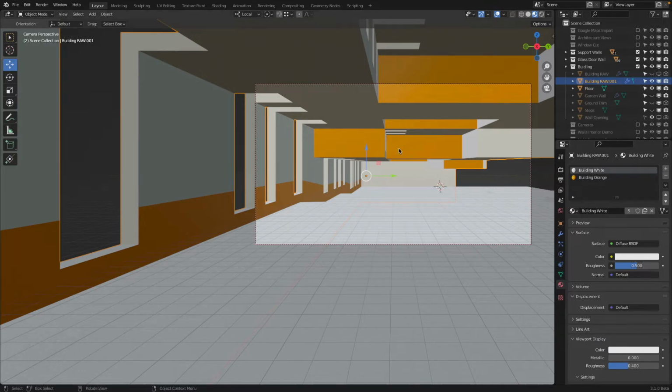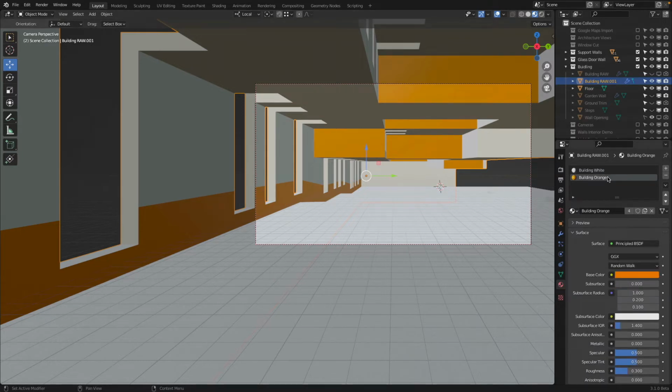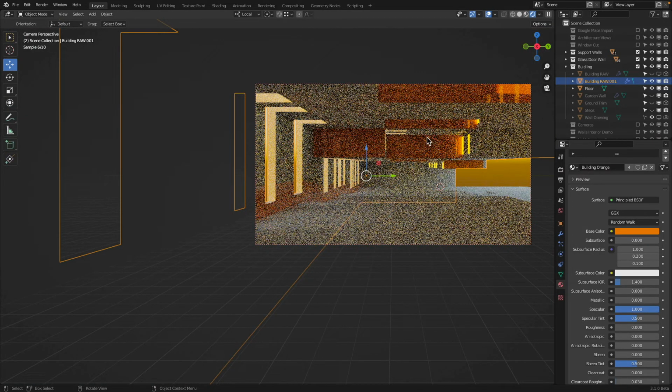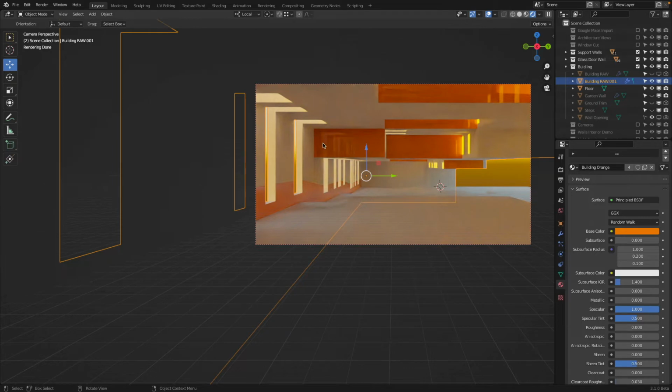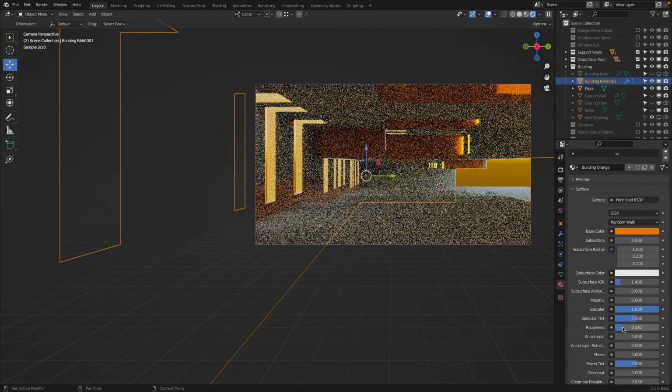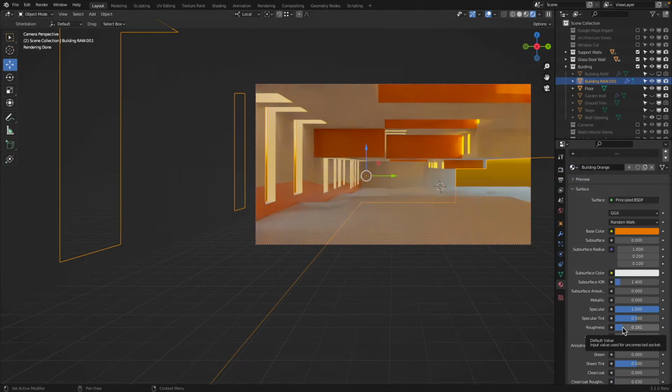And just to reiterate, you have matte material, you also have glossy or semi-glossy material. So if this should be high glossy, then this is a normal BSDF, and we go specular, and the roughness makes sure, if this is now really plastic glossy, you can see the reflections on it. Or if we set specular to 0, it's matte. If it's really reflective, okay, but if we then increase the roughness, the reflectivity is there, but the image is more diffused.